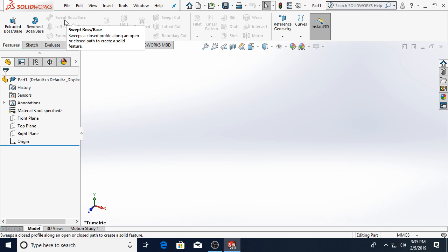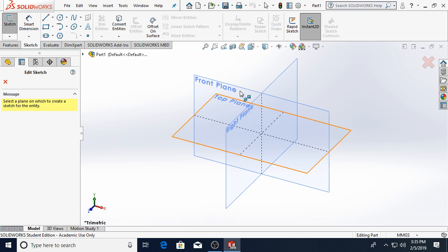2, you have to keep in mind that your sketch to sweep through space has to be positioned relative to the sketch to follow. So in this case, I want to position my sketch to sweep through space such that it is intersecting my sketch to follow on one of the endpoints. Does that make sense? So I'm going to create one sketch on the front plane here, because I want to match these views, and I'll create a second sketch on the plane corresponding to wherever the endpoints of my handle are.